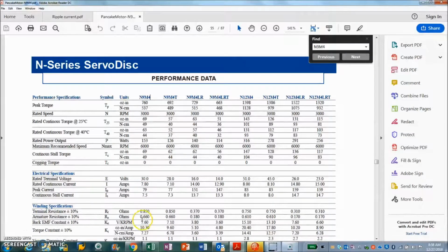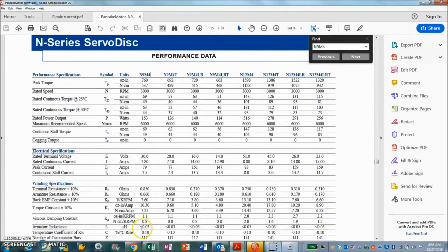Anyways, the unique characteristic of this motor is the really low inductance. This one says less than 30 microhenries. I think we measured it at around 50 with the tool. It also has some winding resistance. The spec sheet that I got on this motor separately said less than 100 microhenries. So not sure what less than 100 microhenries is, but it's probably not more than 100 microhenries.